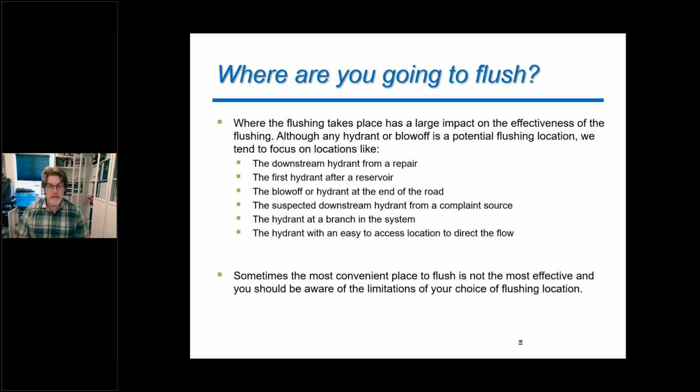One of the big key things, though, is you do need to go check out the area where you're going to flush, because sometimes what looks on the map or in your head like the most convenient place to flush is not the most effective and might have some limitations. Maybe that hydrant at the end of your system is right by someone's driveway, and there's not good drainage for doing a flush there. And so maybe we need to look at flushing somewhere else instead and alter our program.